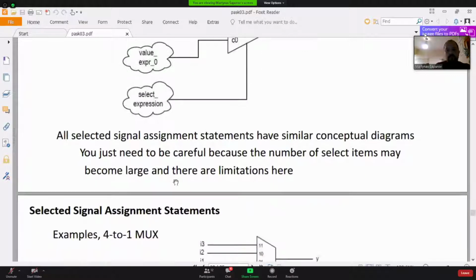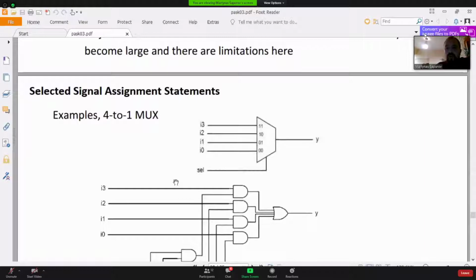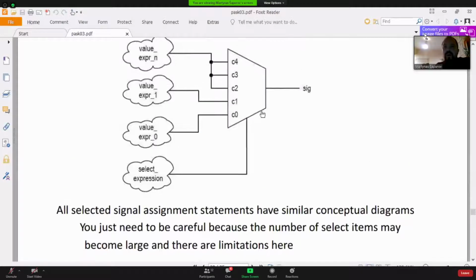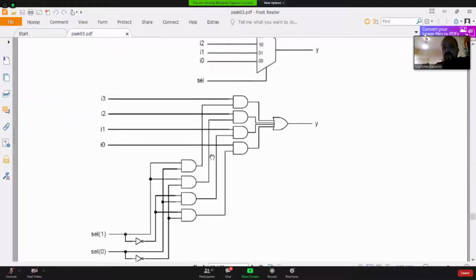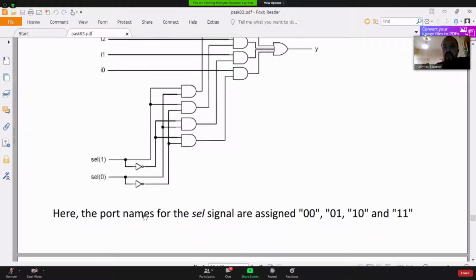So in this case, we are going to employ the multiplexer 4 to 1. We have a 2-bit select signal, and with a 2-bit select signal, here are all our choices. If we have a 3-bit select signal, once again we have more choices. If not all of those choices are specified, we'll connect them like this using others. All will be connected in parallel. As you can see, in this circuit there is no priority routing anymore. And here's how such a multiplexer can be built from logical elements.